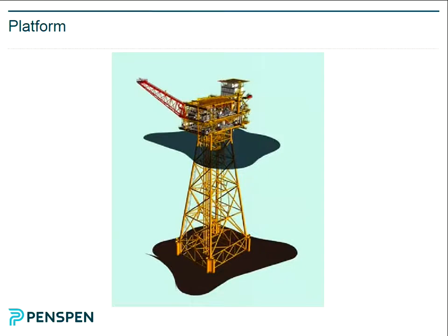And here you've got a number of risers, because you've got probably a production riser, test riser, water injection riser, gas lift riser, umbilical for control, so all going up to the FPSO. And then you've got an export riser, along a subsea pipeline to an SPM, and then the export tanker basically. So you're putting your production equipment here on something that floats.